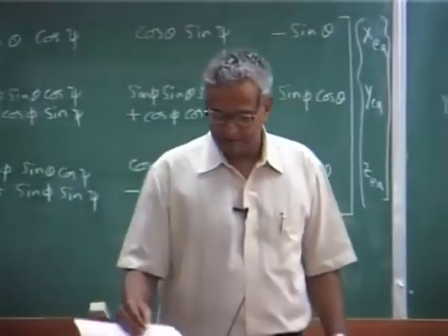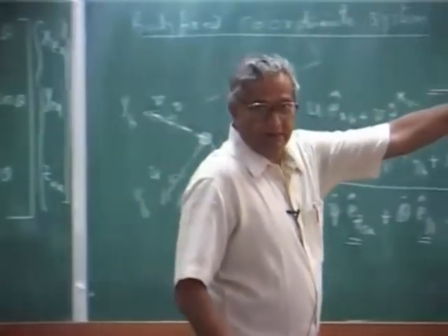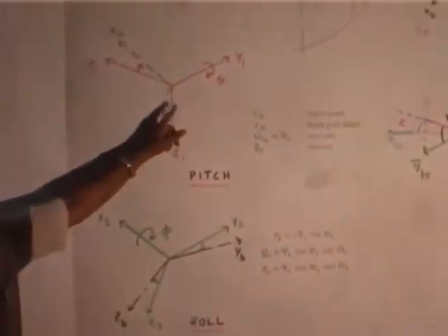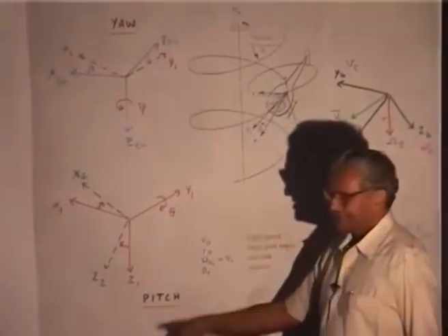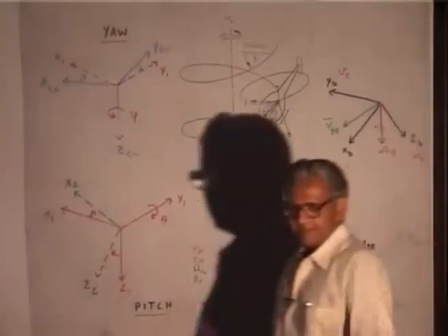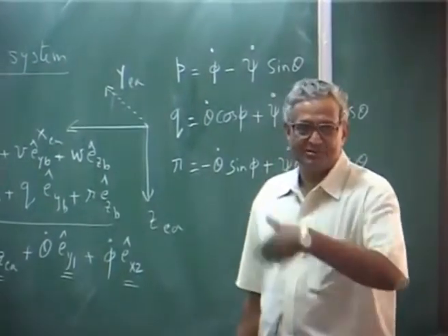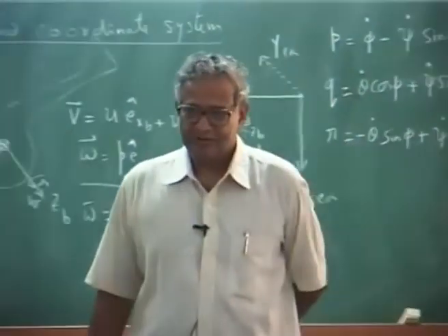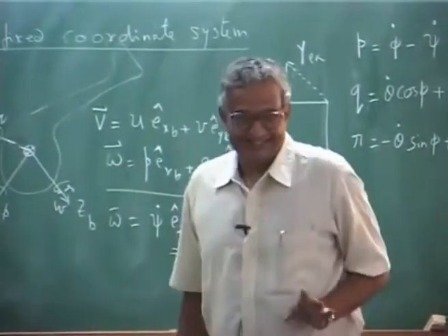Again, like the theta, phi and psi, they are with respect to what point? As you have defined here. Okay. That is why the sequence you follow is the most important thing. This is the sequence we are following. Suppose if you change the sequence, you will find a different thing. Usually that is why I said the yaw, pitch, roll sequence is followed, so that everybody understands the convention, and the coordinate system also they try to use the same.